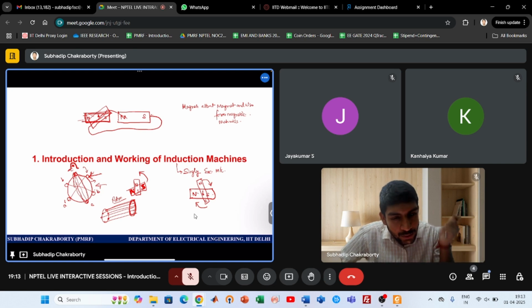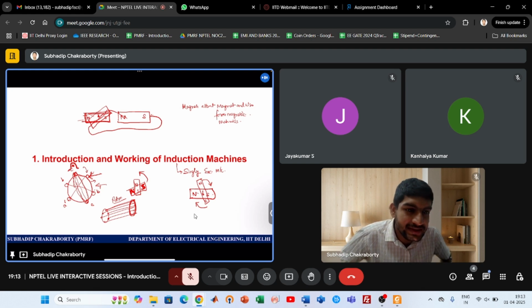Stator has coils. You plug in the three-phase balanced power source, and it creates or generates the field. How? We'll see. But please know it creates the field, and the stator also handles the power. Power means the load it provides for. If it is a motor, it takes the power. If it is a generator, it gives the power. But the power is also handled by the same person, which is the stator, as well as the field. Field is produced also by the stator.